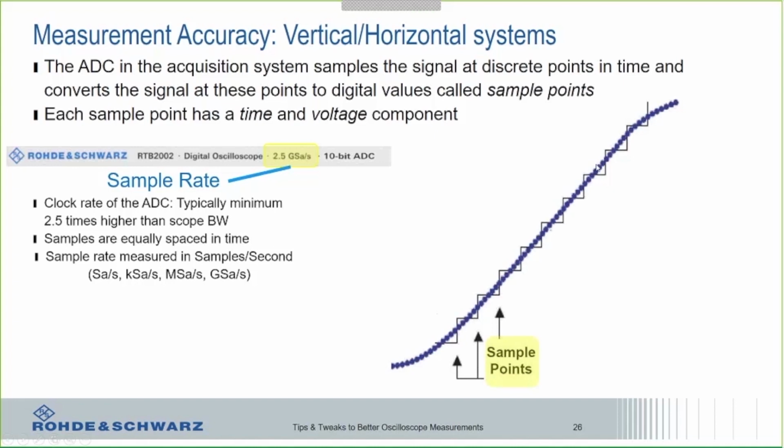And again, if we look, we have the blue signal, and as you go through, not only do we have the vertical component that we talked about before, those different levels, but then we also have the actual sample points in time, and that's the ADC. So basically, the resolution in time of the ADC as it goes through for those sample points.